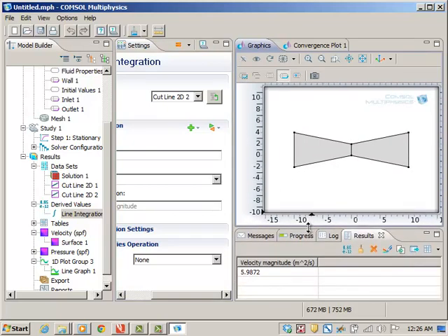it is showing a velocity magnitude integral of 5.98 here. So this is your flow rate. Remember, we are modeling it in 2D, so it is flow rate per unit depth, which is the third dimension. So this value is 5.98. And what is our initial flow rate? If you look at the inlet, its width is 6 units, and we are imposing an average inlet flow of 1, so it's roughly 6. So at this inlet our mass is approximately conserved.